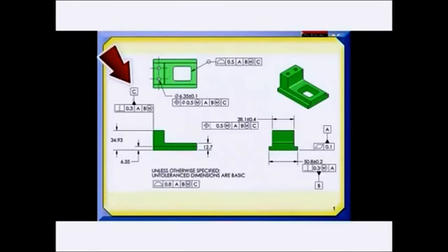Then datum feature C is this back surface. So it has to come up against a plane that's at right angles to the first planes that I've established using A and B. Let's take a look at two different parts in the fixture or setup for this part, where B has been modified at the maximum material boundary, as you see in these feature control frames.